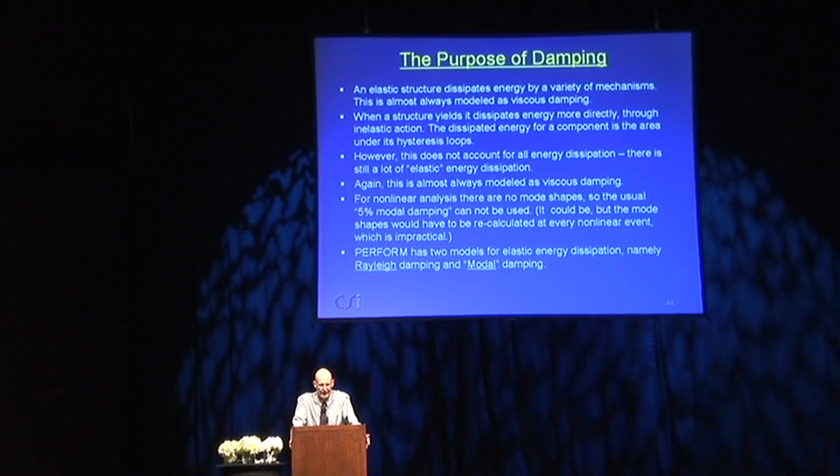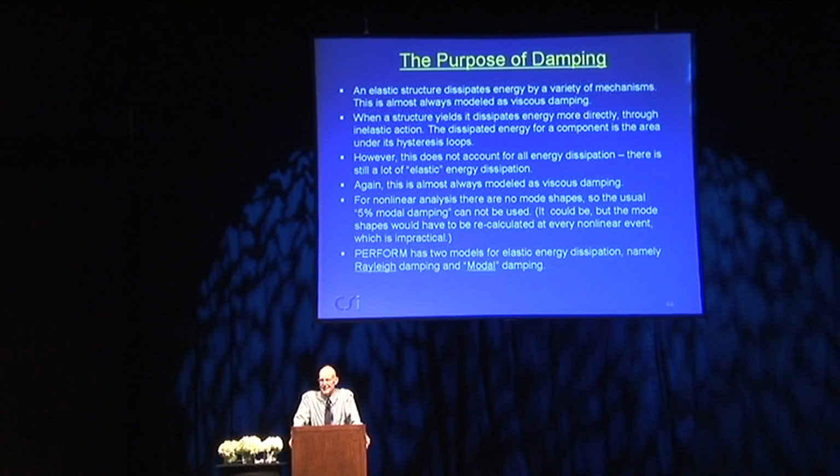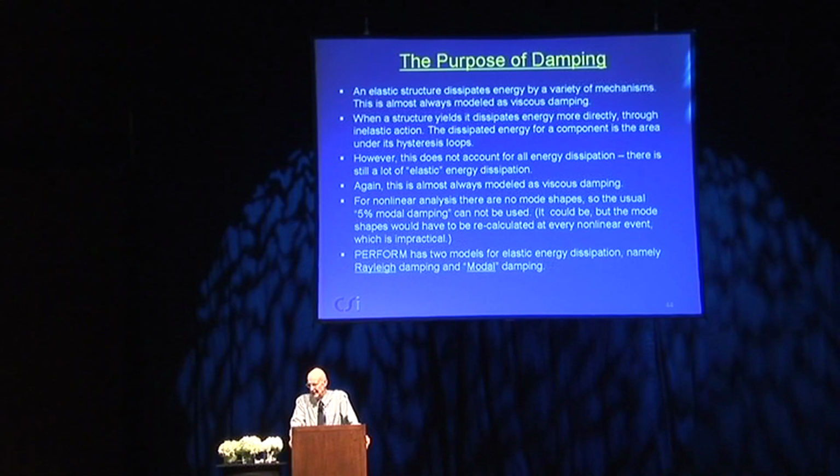If it's an undamped structure, it is going to vibrate, but if it's damped, we know from experience that energy will be lost. It'll be dissipated in some way, and it'll be dissipated by a variety of mechanisms. It could be somewhat inelastic behavior. It could be rubbing of partitions. It can radiate energy into the soil.